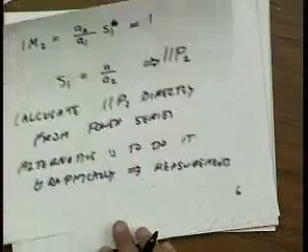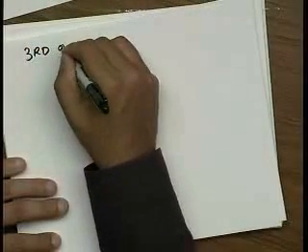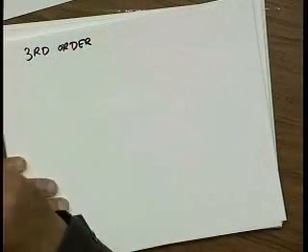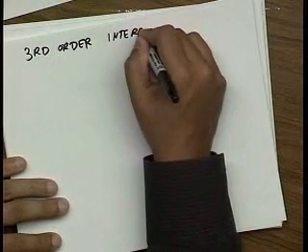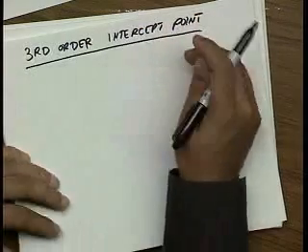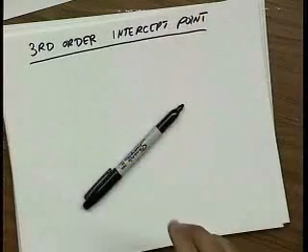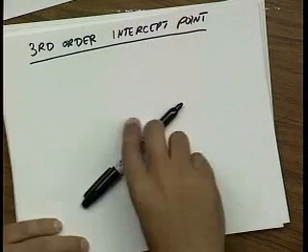Well, a very similar concept is your third order IP point. And in fact, it's a more important concept for most systems. Remember last lecture we talked about second order intermodulation falls at low frequency and at roughly twice the frequency if you have two tones, right?